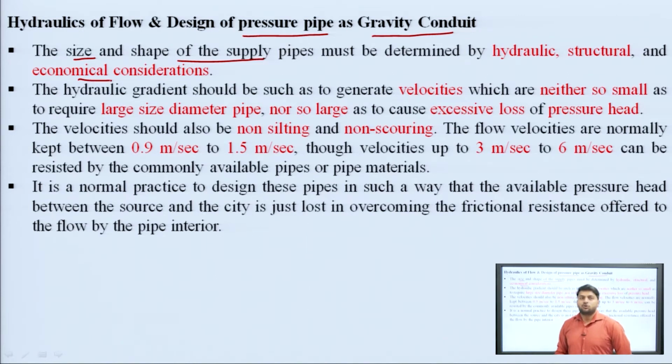Okay? So, for that reason the hydraulic gradient should be such that it generates velocities. The velocity should be such that there should be no silting or no scouring. And another consideration for the velocity is, what should be the optimum velocity.